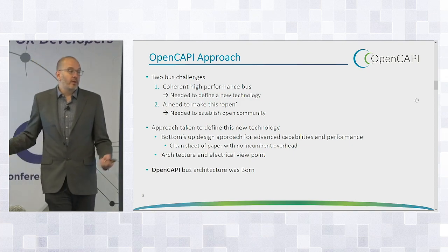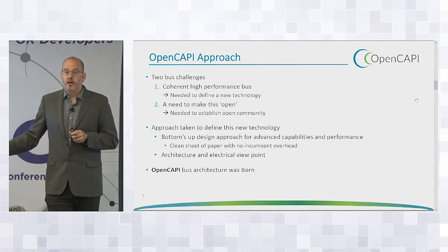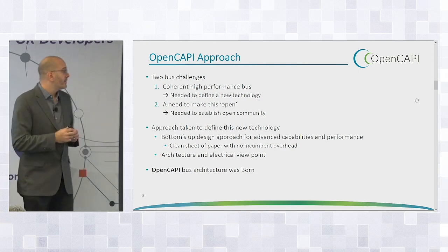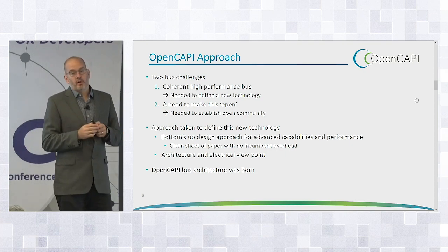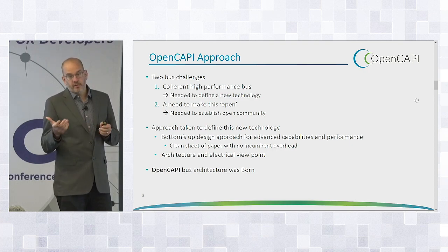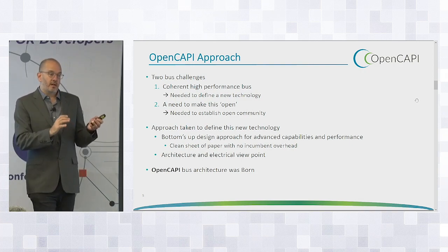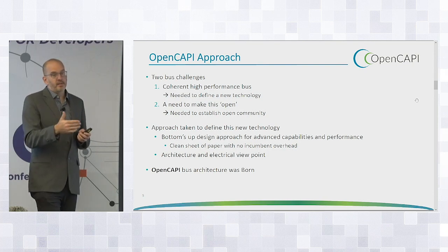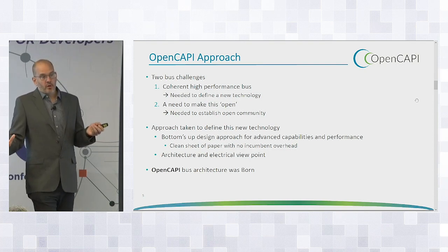And to do things involving coherence, you need virtual channels. Those are expensive in PCIe ecosystems. You also need different types of formatting and templating. So we started with a clean sheet design that we based around our previous work in attaching low latency memory devices, and also the previous work we did in accelerators to build this device where you could have a very thin layer in the accelerator that would talk across an open interface with low latency. We had to go clean sheet though, because if you looked at the way the PCIe packets were made, the way they were encoded, that was sort of incompatible with what we wanted to build.